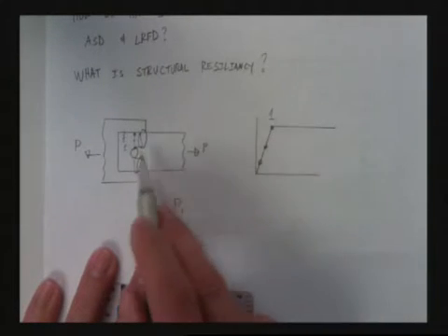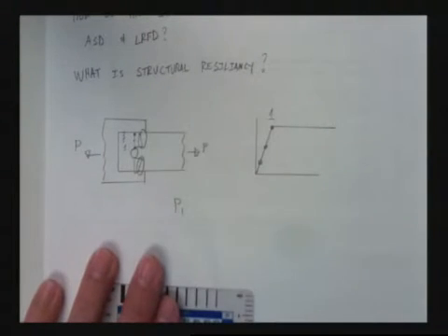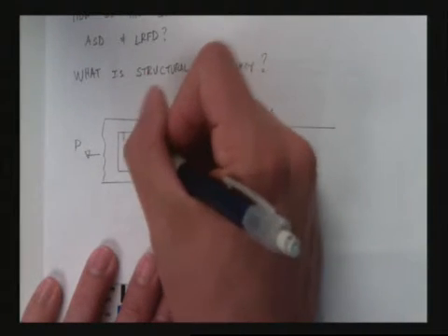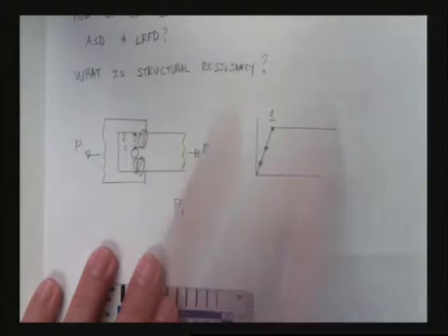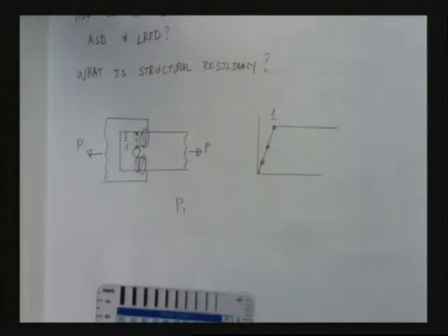So the idea is that we're going to go all the way through the strain hardening, and we are going to take that benefit into account. The reason we're able to do that is because the yielding is occurring over such a small area that it's not that big of a deal to the structure. You with me? We'll talk about cases today when that yielding happens over a much larger area of the structure, and that's not something that can be ignored.